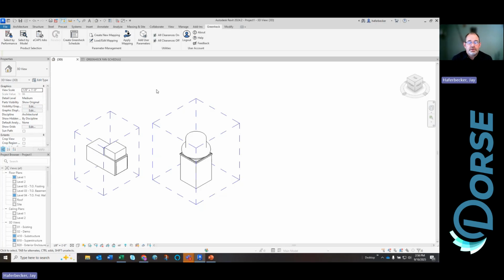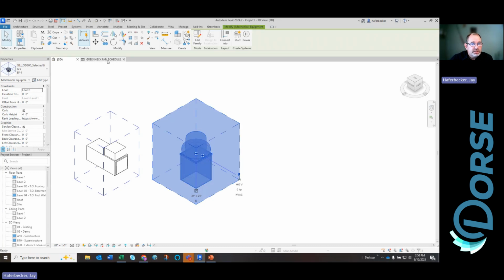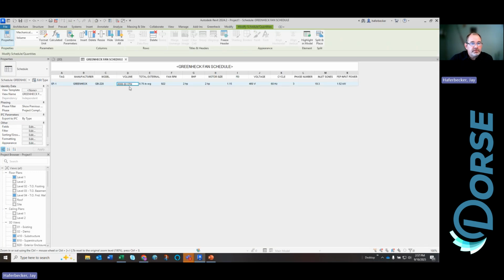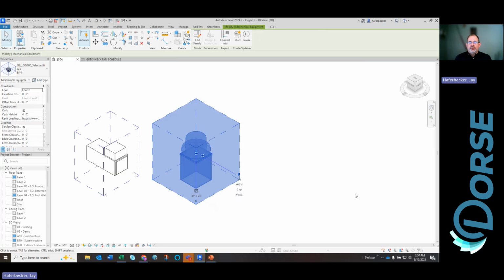Now, the last thing that I wanted to talk about, because we're almost out of time here, is that your jobs probably evolve over time, right? So you probably made this selection here, for example, and we did 6,000 CFM, right? But what happens when I'm expanding this office space or whatever, and now we have to get an extra 300 or 500 CFM out of that fan, or maybe we added 2 extra elbows in the system. We've got a 1/4 inch more ductwork or whatever your use case is, right? So normally what you do is just hit delete and start all over again. Well, we made it really easy.